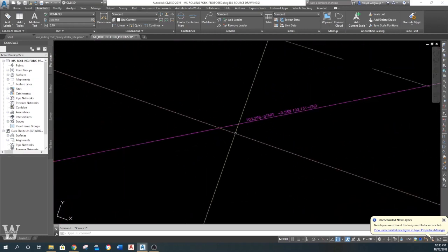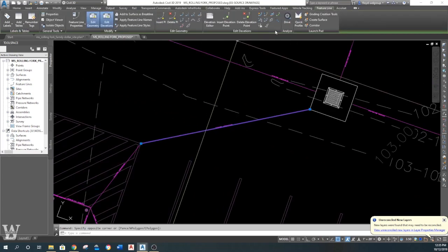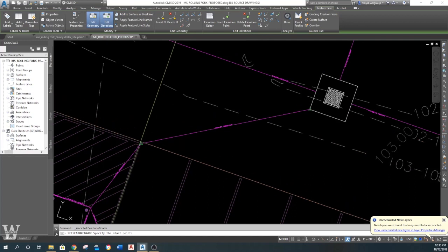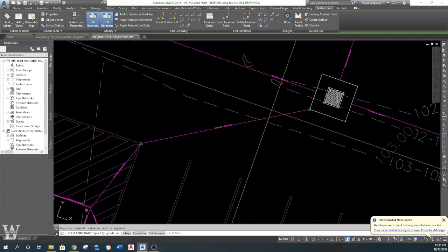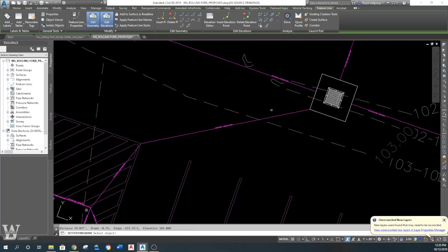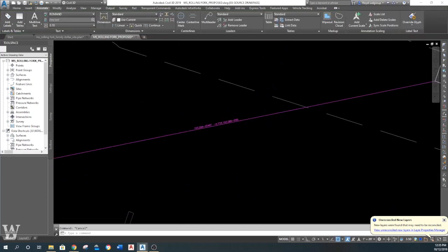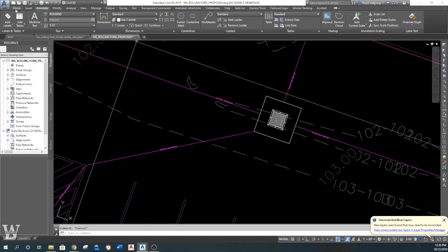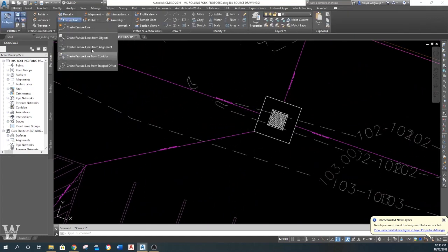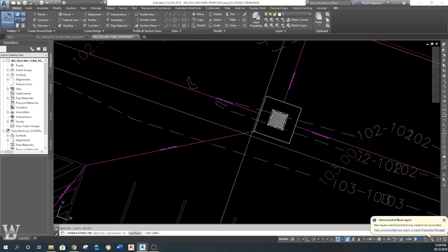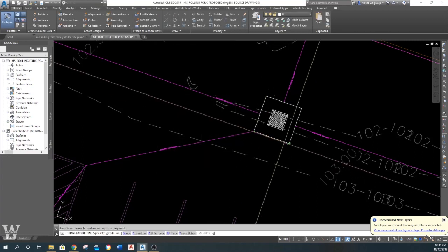what we want to do is we want to go from here, on our grade select, go from here to here at minus 0.75 right there. See what that does. That gives me 103. Let's draw a feature line: home, feature line, create feature line, okay. And we're just going to go around here to grade 0.